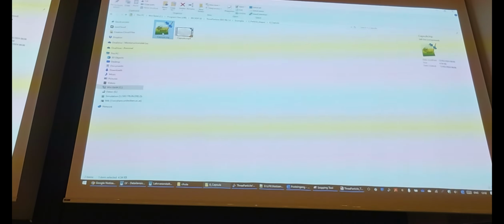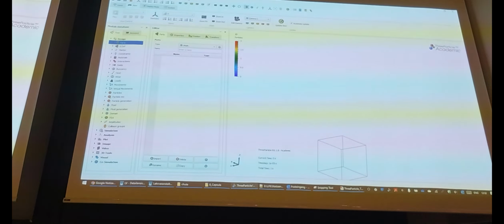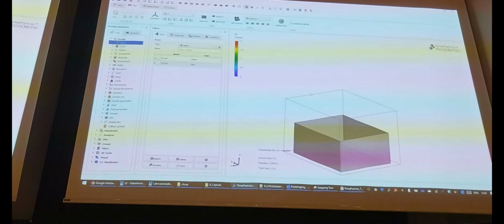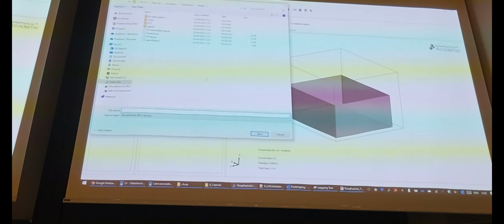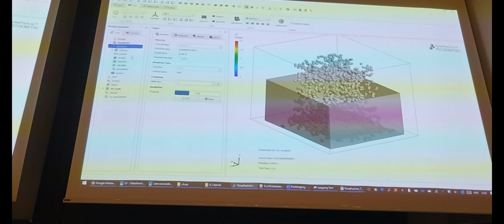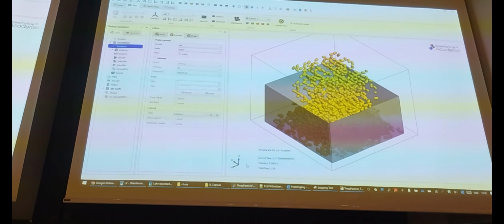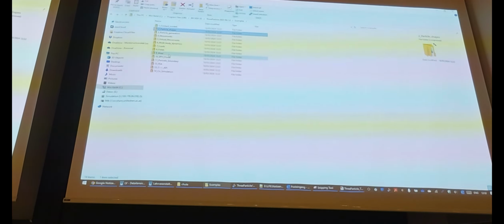So this EMP file, you can import that. Let me give an example here. If you say file, import keyword file, and use that capsule input file, you get exactly that input file. If you start the simulation now, it's similar to the tutorials, and gives you exactly the video that you've just seen, but in your simulation. So you can use every example. There are lots of them. This is one, capsules. There is something on, I don't know, for example, fluids, you addressed that.